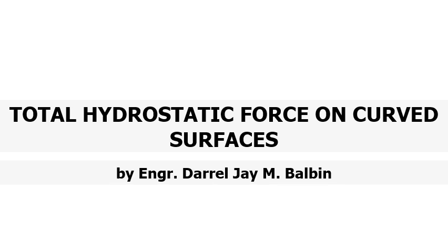In this video, I will solve sample problems in total hydrostatic force on curved surfaces. The tank shown is 3 meters wide into the paper. Neglect atmospheric pressure. Unit weight of water is 9.79 kilonewtons per cubic meter.